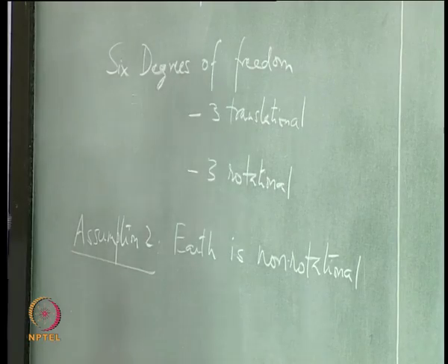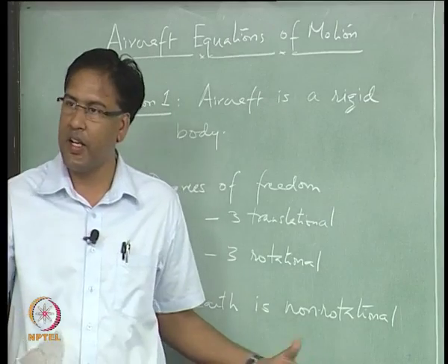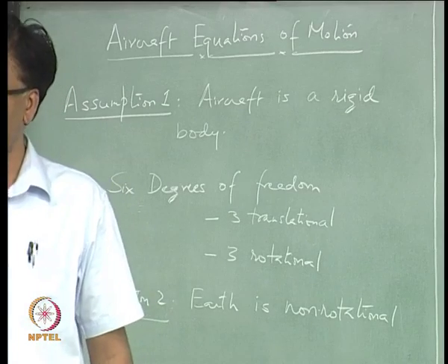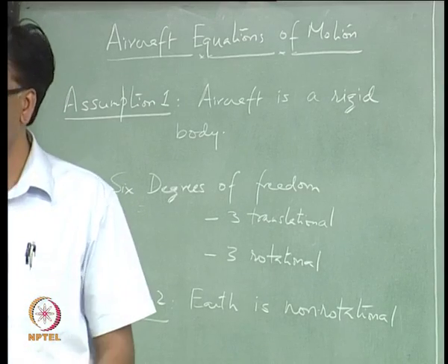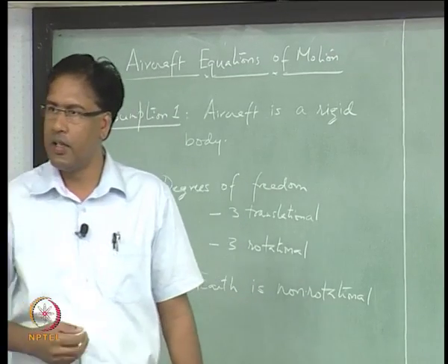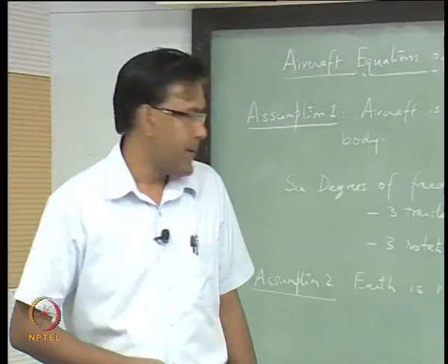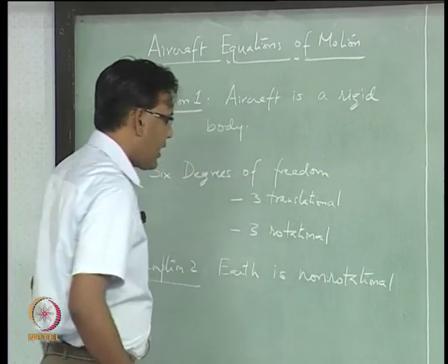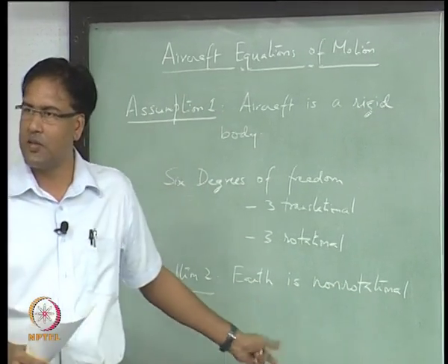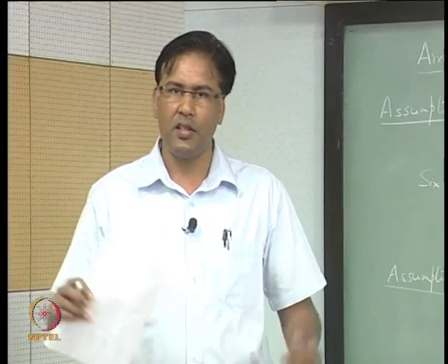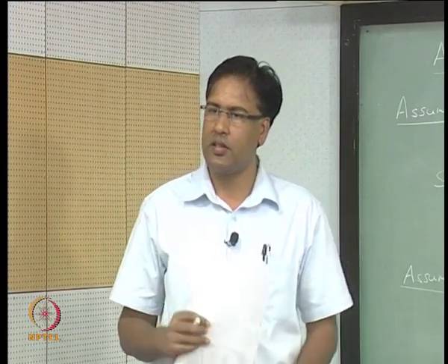I am writing non-rotating specifically because we do not want to include the effect of rotation of earth on the aircraft dynamics, okay. That will be negligible because we are working at lower heights, right, and for our engineering purposes, this will be sort of a valid assumption.